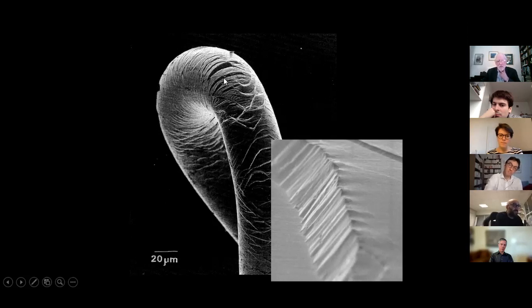So this wire was bent, you then let go, you get a certain amount of elastic spring back, and you get regions where you've got neighboring shear bands which are very close to each other. The shear bands themselves are momentarily liquid-like in their flow behavior. And so when you let the wire go and this surface goes into some compression, you might just have a little sliver of solid trapped between two liquid-like layers that pops out under the compressive stress when you let go of the wire.